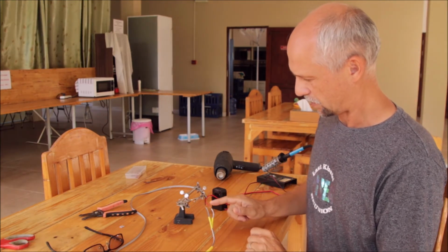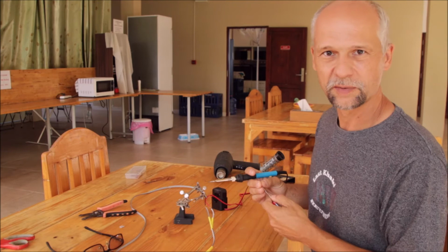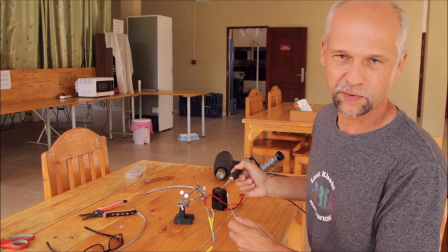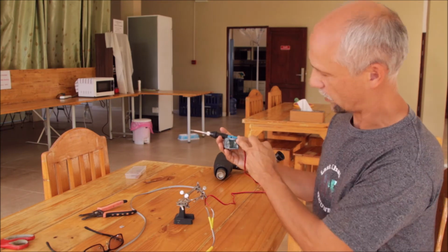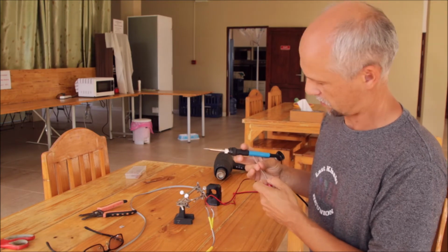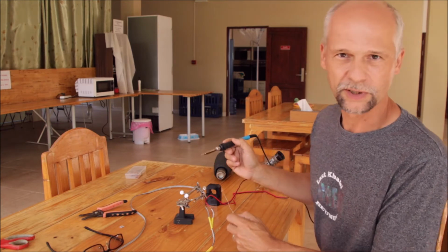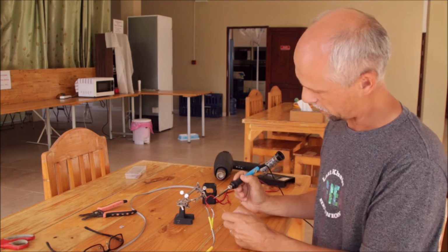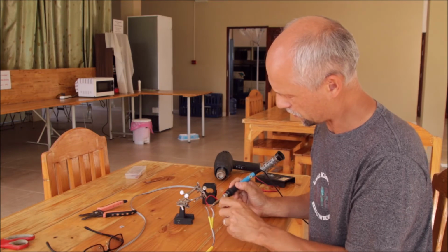So I have twisted the wires together. As I said, there's no need to think about a particular order of the connections. It's a 50-50 chance that later on the CT will be connected according to this arrow which is shown here. If it's wrong, then it's your choice: either change the solder connections again, or you just turn over the CT with your cable wherever you do the measurement.